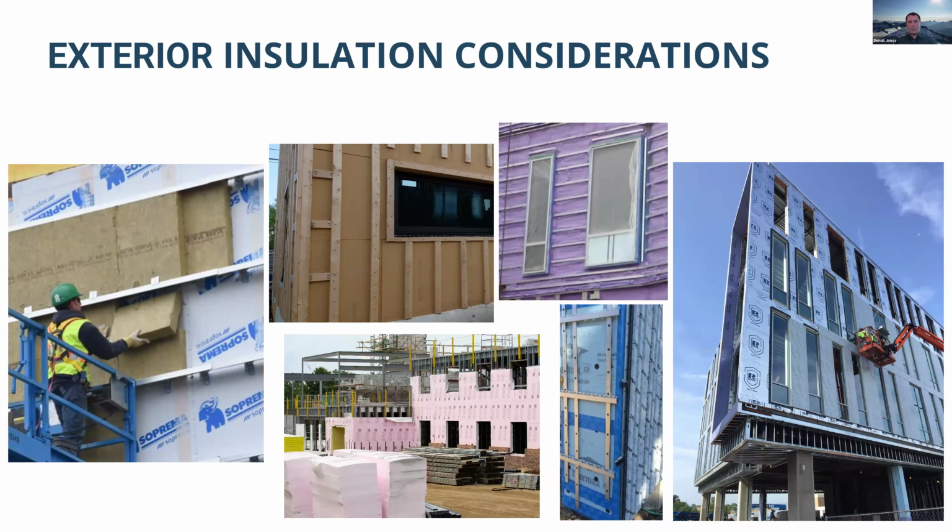This is going to be a higher R value per inch, but it's vapor impermeable. It's also quite water resistant as well. Or this is just spray foam in between these horizontal girts with clips behind them. So lots of different ways to do it. Again, it's going to be different depending on climate zone, fire requirements, how much R value you actually need, et cetera. There are lots of different variables between what type of exterior insulation you might need.